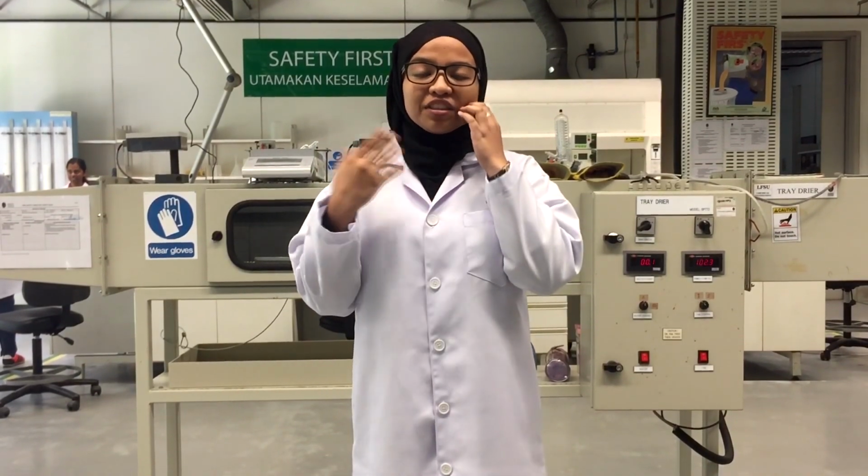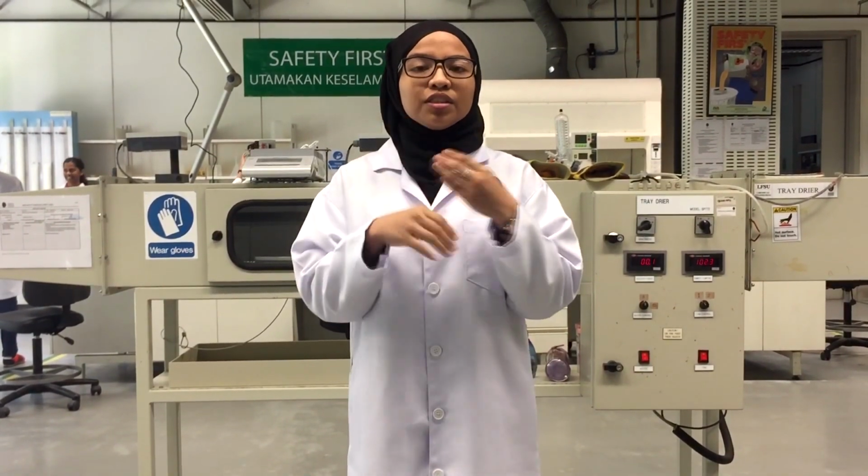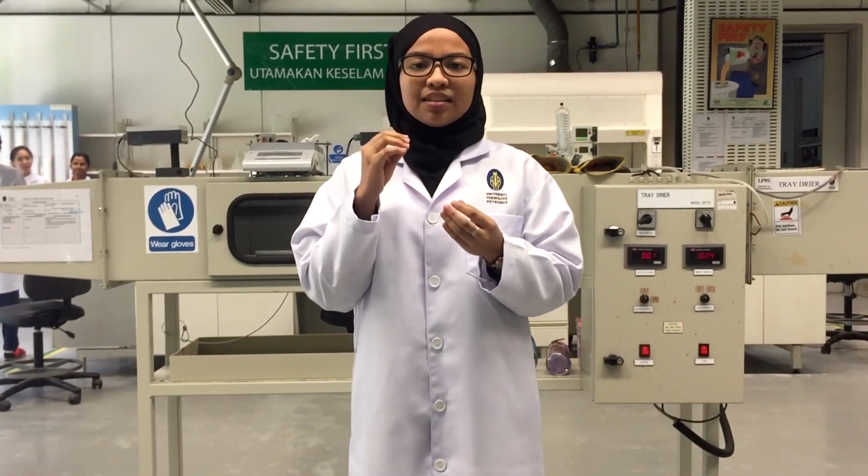In conclusion, there are two critical aspects in the drying process. The first is heat transfer and the second one is mass transfer. Heat transfer is when liquid is being evaporated, while mass transfer is when the vapor is being transferred into the surrounding gas. There are two parts of this experiment, the first part is when we use different air temperature with the same air velocity. The temperature is being controlled by heater A and heater B, where heater B has a higher air temperature than heater A.